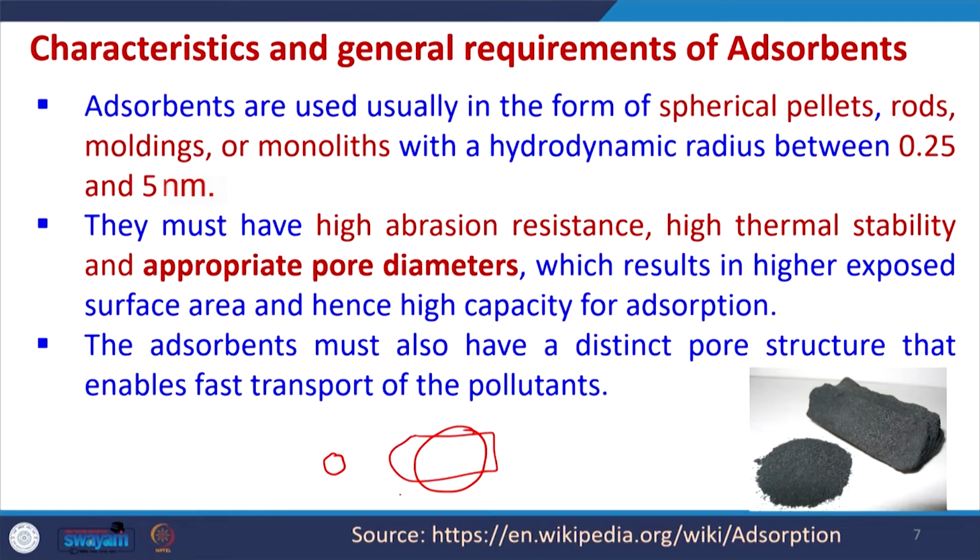So, this dye molecule cannot go inside the average pore diameter of the adsorbent. Under that condition the selection of adsorbent has not been correct, because the dye molecule cannot go inside the adsorbent which has a pore diameter lower than the molecular size of the adsorbate itself.